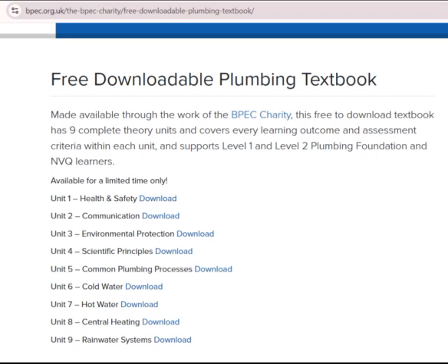2. Venting of gas build-up within heat emitters. Gas build-up can be from either of the 2 points noted above. Take care when venting radiators on existing systems, especially if the gas build-up is caused by hydrogen, as it is highly flammable.